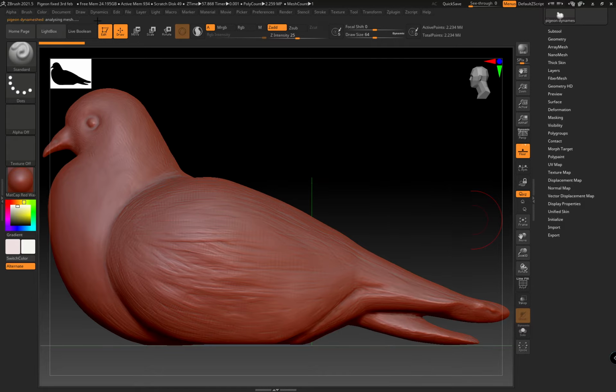You'll see that there's a kind of progress thing happening at the top. Decimation can take a while, it can take a few minutes, depending on your active point count and depending on the RAM or processor in your computer. Okay, so you just have to be patient. Try not to click or scale or zoom or anything whilst the decimation is being performed, because it does have a tendency to crash the computer if you do that.